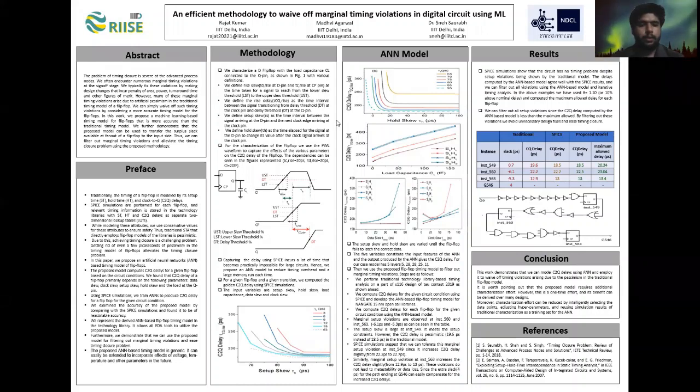Now comes the methodology. For our methodology, we define certain basic definitions of rise skew, rise delay, setup skew, and hold skew. For this, we simply use a D flip-flop with the CP and Q pins, where the load CL is attached to the Q pin. We consider UST, the upper slew threshold, which is 80%, LST, the lower slew threshold, which is 20%, and the delay threshold, which is 40%, for our definitions. So this is TD rise, this is TC rise, tau is the setup skew, tau is the hold skew, and TCQ rise is the delay.